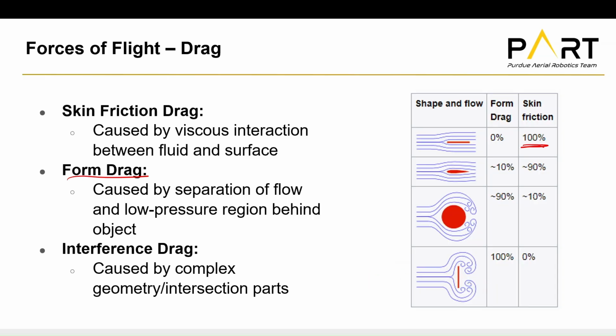Now you see with an airfoil, you have a mix of form drag and skin drag. I hope you can see that intuitively. Now you have some dimension in this vertical direction, and you have a lot of dimension in the horizontal direction. Your sphere mostly has form drag, because form drag takes precedence here, right? I mean, you have a giant wake behind a sphere. And then your flat plate, like I said, has zero skin friction drag.